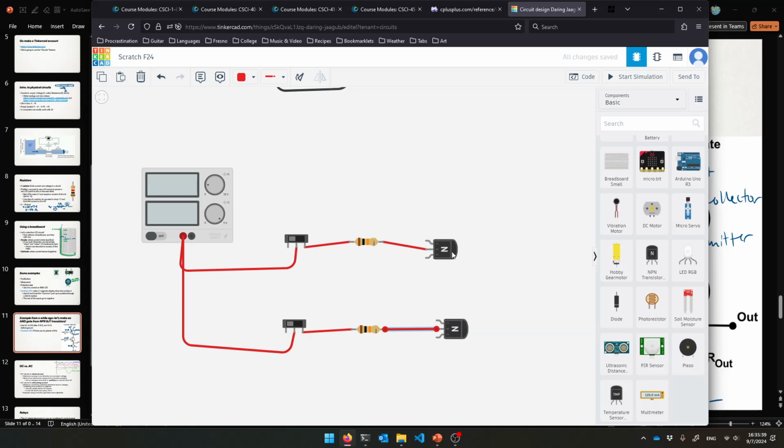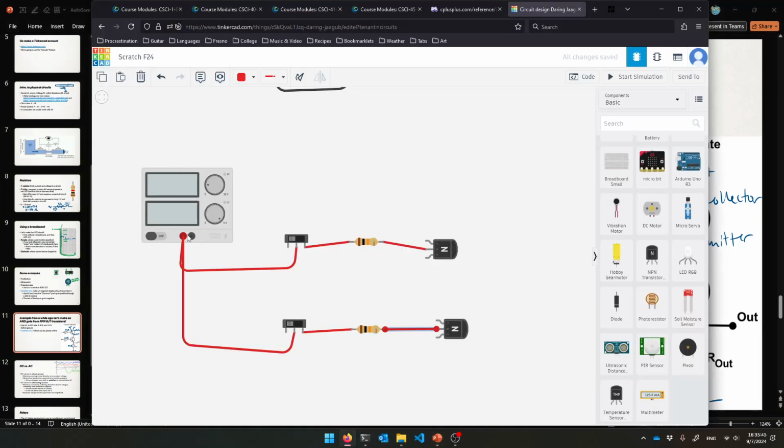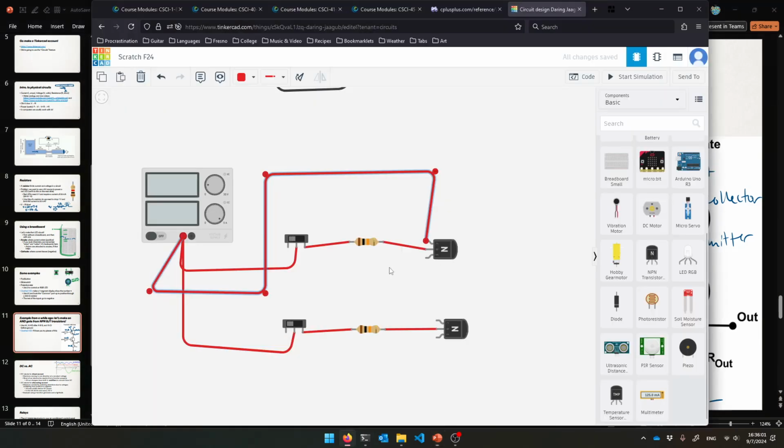So now the goal is to eventually get power all the way from down to here. So we have to hook into the collector from power itself as well. We're giving it the full power, not resisting it at all. I don't know the best way to make this pretty. So it's coming from the top now, I guess, collector. And we connect the emitter of this one to the collector of this one. Cool. I want them to be in series like this.